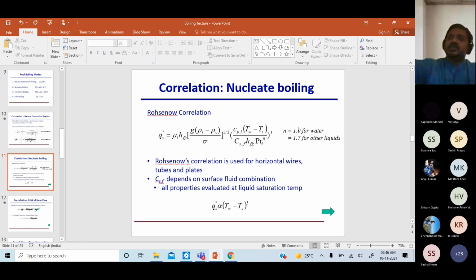Because in forced convection, conduction, even in natural convection, it was always proportional to delta T only. In natural convection, you can say h is also proportional to delta T, so overall Q is maybe delta T to the power, I don't know, 5/4 or so, but not cubed.